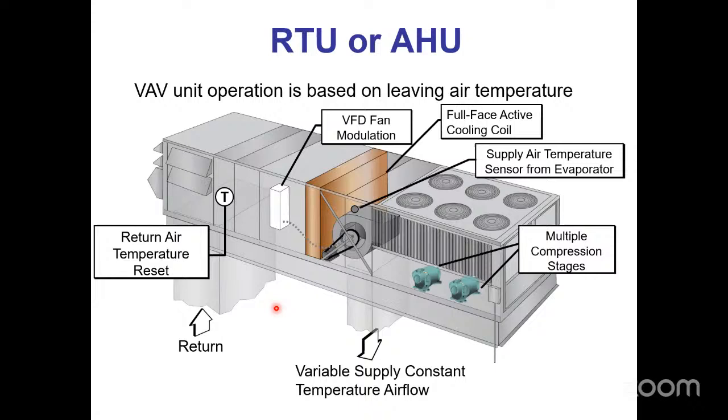It will die. The VAV system, as you're going to find out, we're controlling it to maintain a specific discharge air temperature, 55 degrees. And if I don't have enough stages to do that, it ends up hunting and it bangs one compressor on, off, on, off, and just beats the hell out of that thing. So you definitely cannot use 2 or 3 stage machines to do VAV control. It's got to be bare minimum 4 stages of compression or larger.